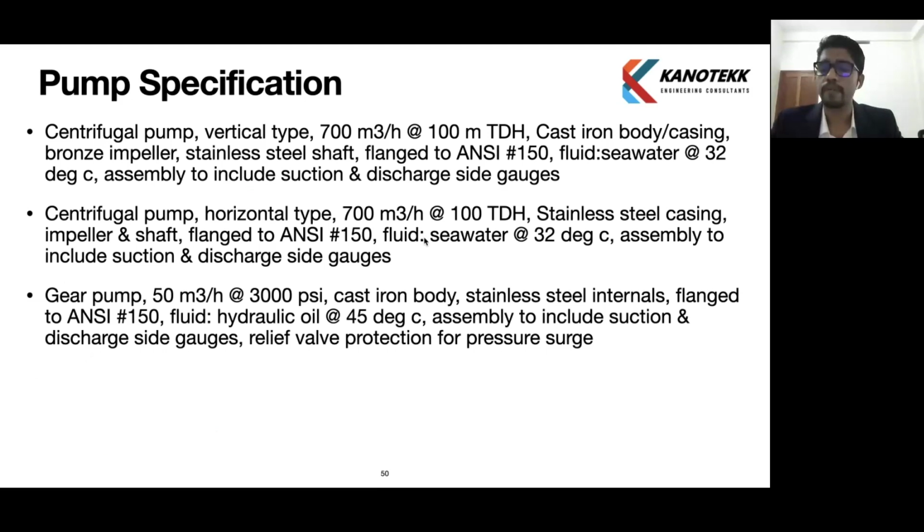And positive displacement pumps like gear pumps, lobe pumps, piston pumps, etc. are used for higher viscous fluids like oils, hydraulic fluids, or thicker viscous fluids. Similarly, for the food processing industry or pharma industry, etc., we use a lobe pump. So there is a difference.